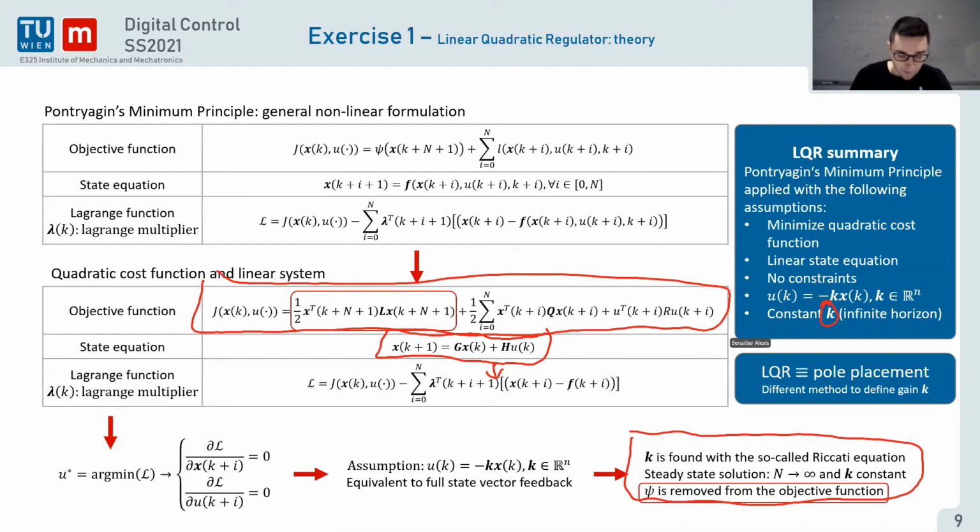We've seen that this term is not here, so we're just minimizing the reference tracking and the input effort. Input effort is how much input we need, and reference tracking is how close we are to the reference value or the desired value, integrated over the trajectory, so making the summation at each sample time.